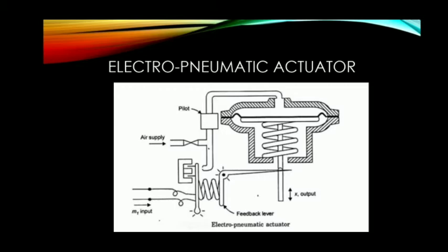automation. Electro-pneumatic control consists of electrical control systems operating pneumatic power systems. In this, solenoid valves are used as interface between the electrical and pneumatic systems. Devices like limit switches and proximity sensors are used as feedback elements. Electro-pneumatic control integrates pneumatic and electrical technologies, and is more widely used for large applications.